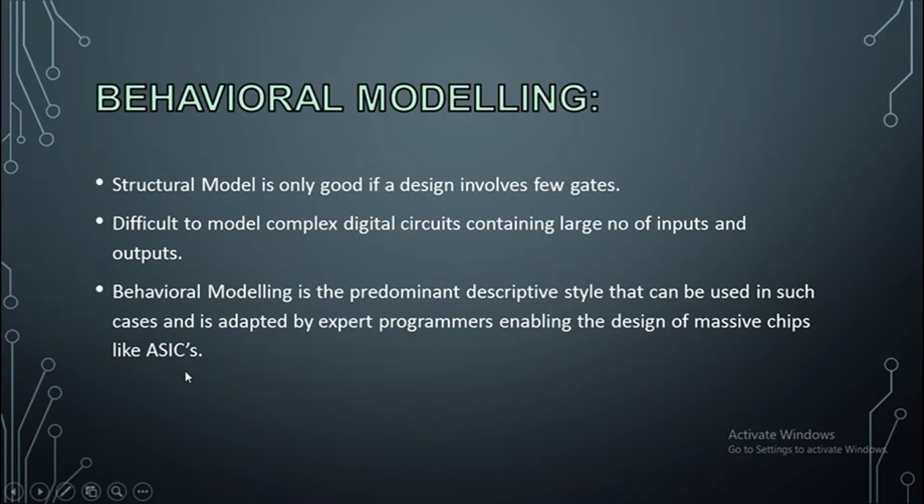That's why we are going to use behavioral modeling in many of the future tutorials, because we are going to design very complex circuits as well. For the beginner level, structural modeling is good, but when complex digital circuits are required, behavioral modeling is very acceptable.